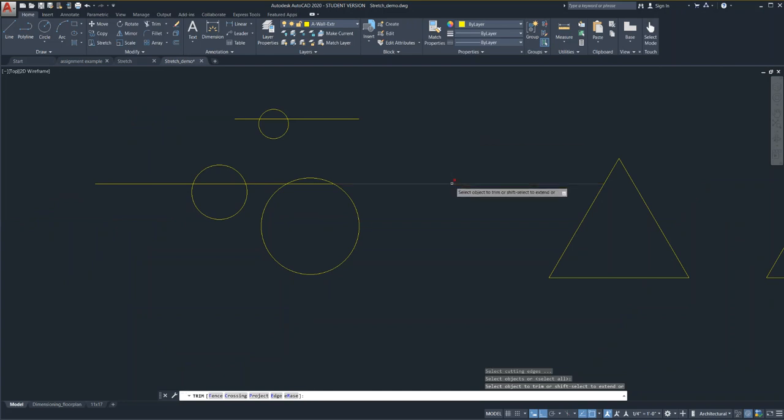I don't have to just pick to trim or extend either. I can use a selection window, so you can see now it goes away. Okay. The long version of extend is the same as trim. So I can type EX and I can hit enter one time. Okay. I can select a line I want to extend my other line to. I can select a boundary, click, enter, and now I have forced this line object to go to that. Okay, escape, U, undo, enter.